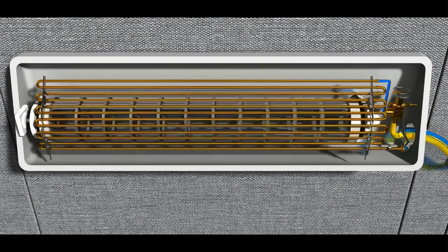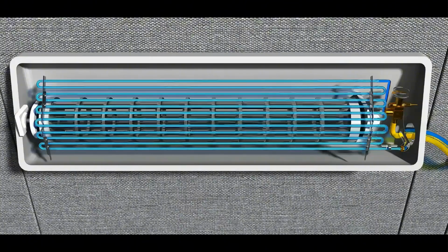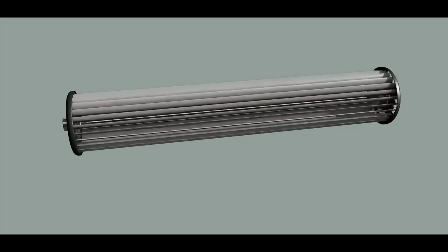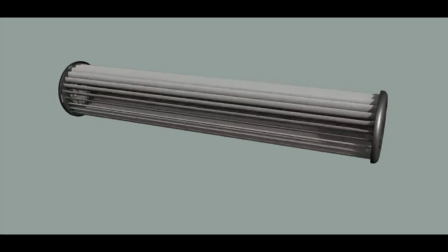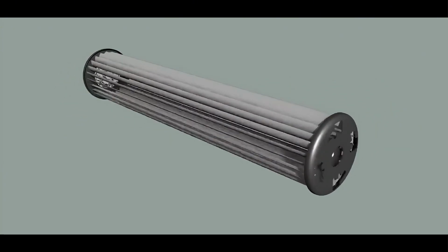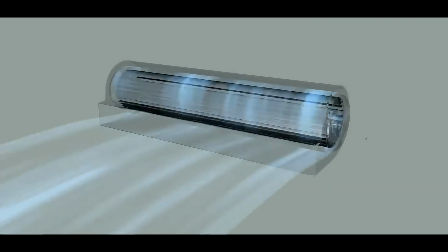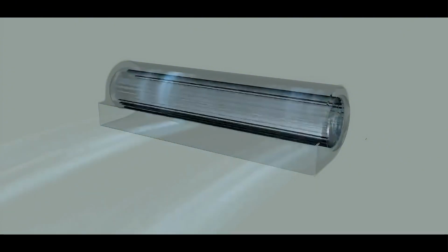A refrigerant passes through the pipes of an evaporator and takes away heat in this process. As the fan underneath starts to operate, warm air in the room is sent to the evaporator, and cooled air is emitted. Fans used in the indoor unit of an air conditioner are shaped as a cylinder, rather than the more familiar version of a propeller. Such a type of fan is called an impeller. As wall-mounted air conditioners cannot take up large space, impeller type of fan is used instead of propeller type.